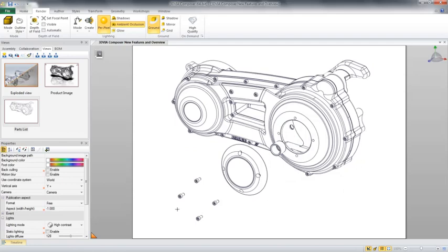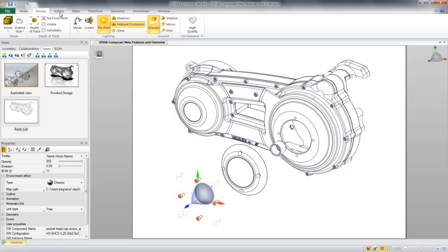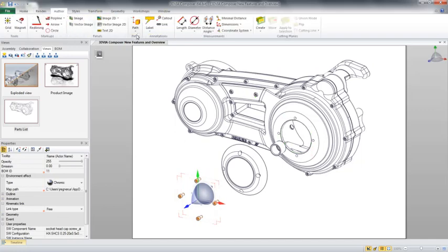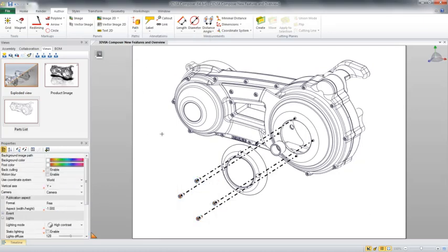To show how these fasteners go into place, we might want to add some trail lines. This is where the authoring tools in 3DVIA Composer come in. The associative and non-associative paths are a great way to quickly and easily create trail lines on our design. However, as you can see, they appear over our geometry in some cases, and they don't necessarily match our styles.